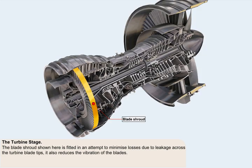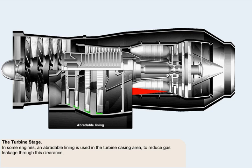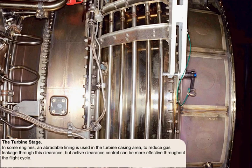The blade shroud shown here is fitted in an attempt to minimize losses due to leakage across the turbine blade tips. It also reduces the vibration of the blades. The clearance between the blade tips and the turbine casing varies because of the different rates of expansion and contraction of the materials involved. In some engines, an abradable lining is used in the turbine casing area to reduce gas leakage through this clearance between the blade tips and the turbine. But active clearance control can be more effective at maintaining minimum tip clearance throughout the flight cycle. This picture shows its use on an American engine.